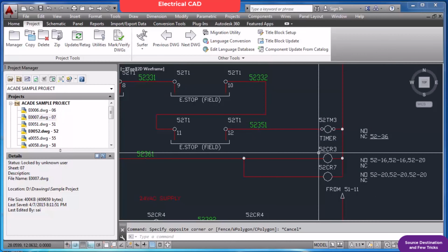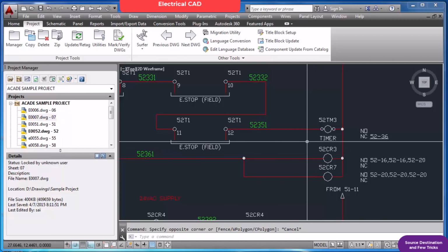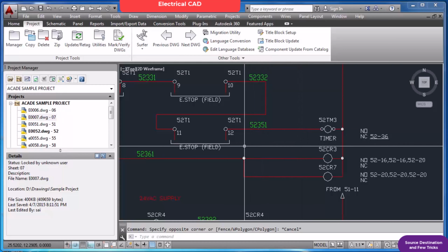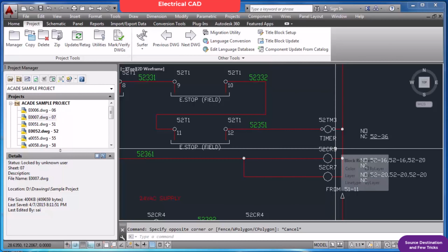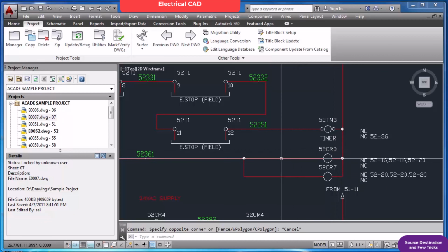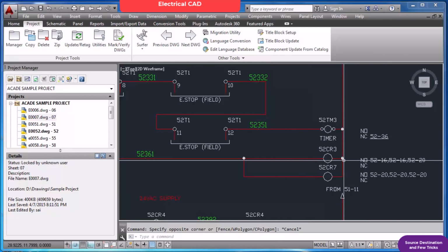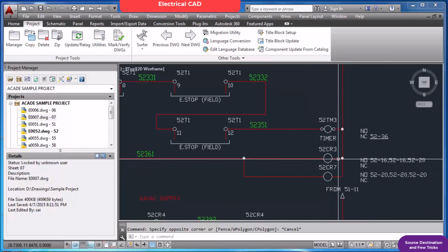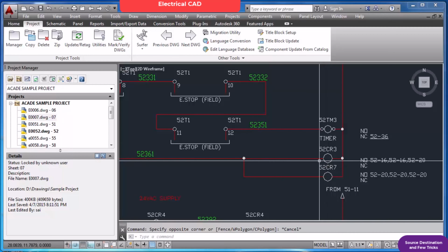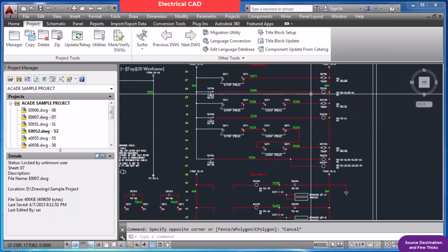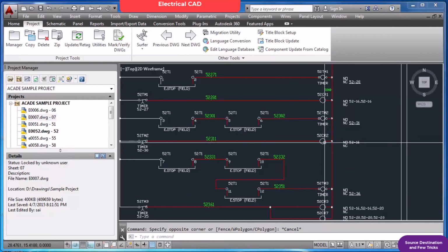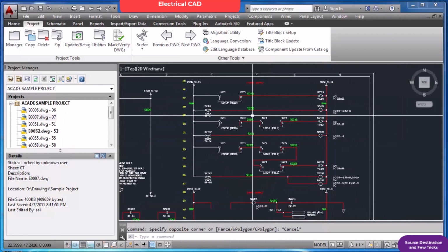That relay was with 4 NO contacts, but while making the schematic diagram I came to know that I need more contacts, and unfortunately I had ordered one relay with 4 NO contacts. In that case, what I have done is insert one more relay in parallel with this particular relay. So basically I am controlling 3 relays in this top circuit.